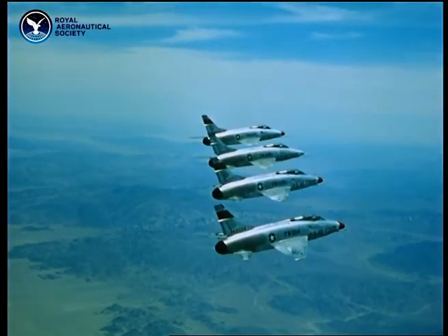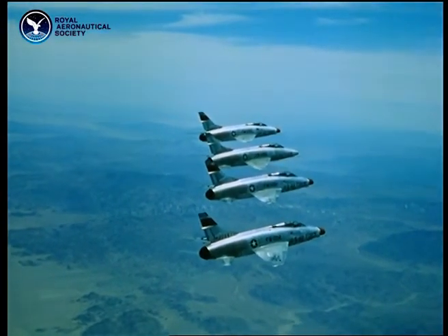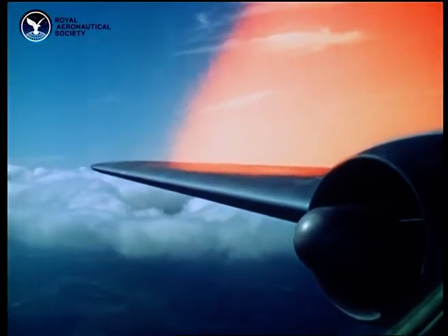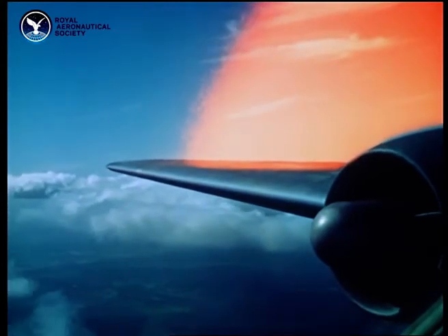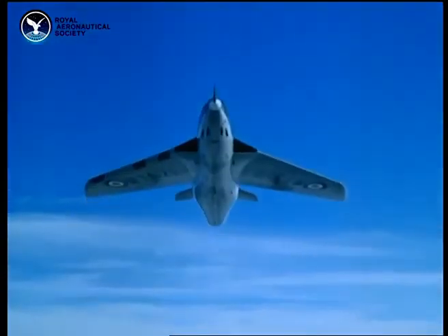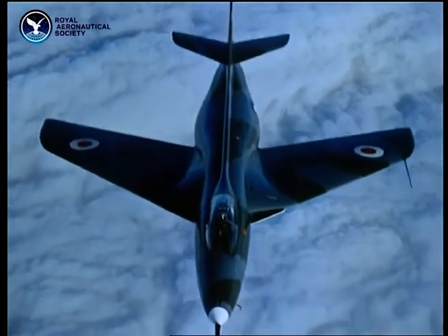All these improvements in design are reducing shock stall troubles in the difficult earlier part of the transonic range. Still faster flying is only possible when wave drag can be reduced. The drag caused by the shock waves changing kinetic energy into heat. A new design principle helps to do this. Area rule.